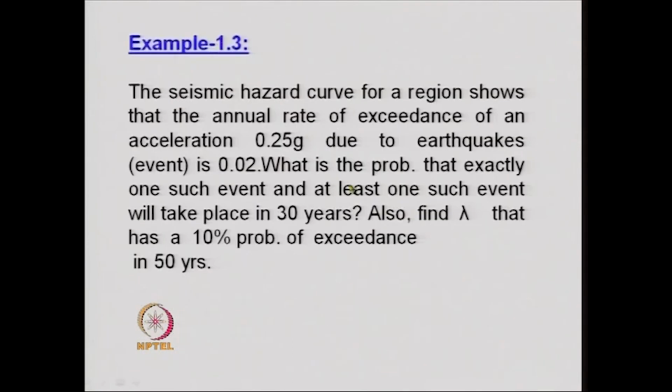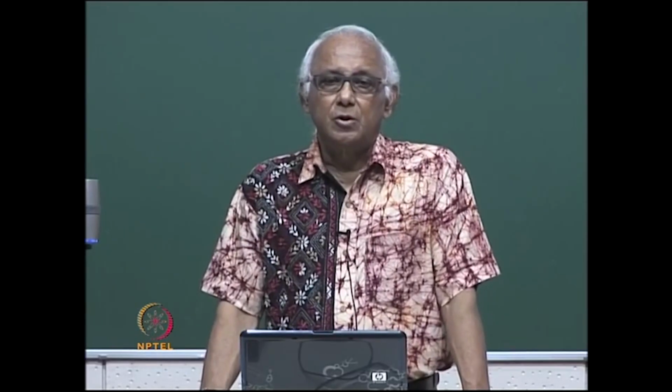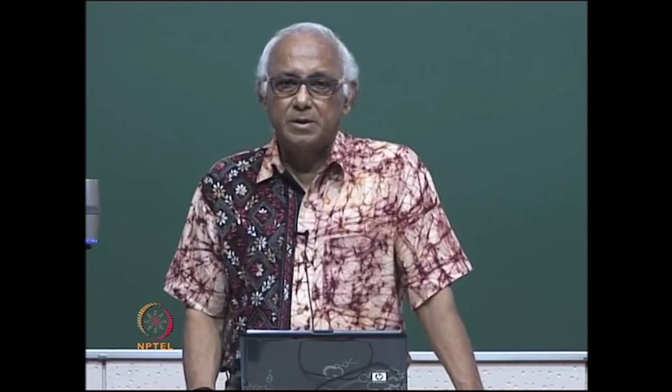So this is about PSHA, and therefore we can see that by drawing what we call histograms showing the probability of occurrence of magnitude of earthquake and the probability of occurrence of certain epicentral distance, and using the pertinent equations, one can obtain the seismic hazard curve for a particular region drawn for a seismic measurement parameter.